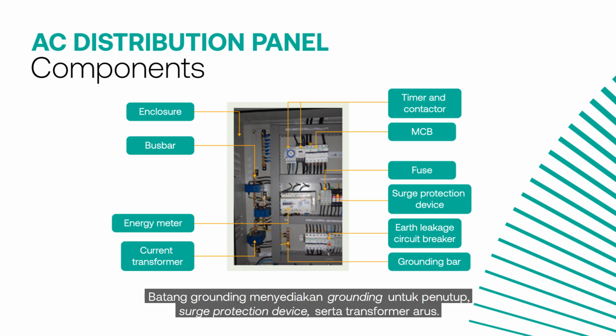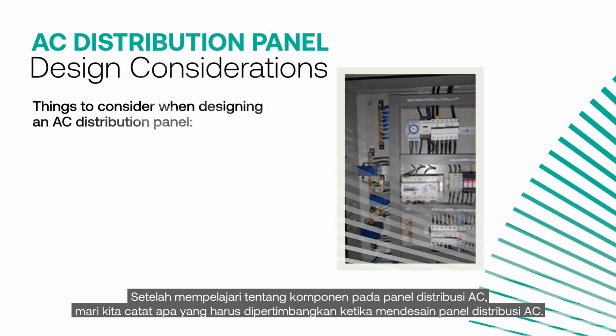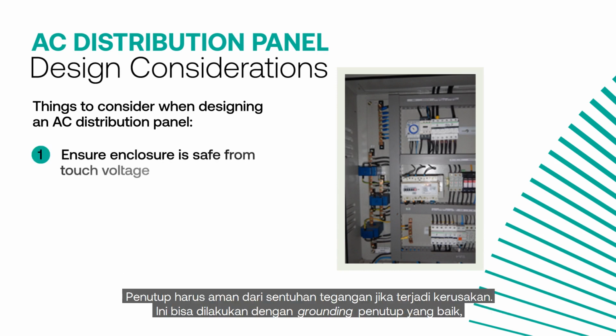Grounding bar provides grounding for the enclosure, surge protection devices, as well as current transformers. After learning about the components in AC distribution panel, let us take a note what to consider when designing AC distribution panel. Enclosure should be safe from touch voltage in case of fault.